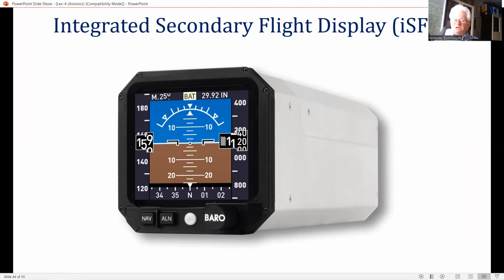The microprocessor computes the aircraft attitude from the gyro and accelerometer outputs, and altitude and airspeed from the pressure transducer output. The system operates from the 28-volt supply, which is supported by the emergency battery. The integral power conditioning electronics are designed to cope with the variations in the battery supply voltage.